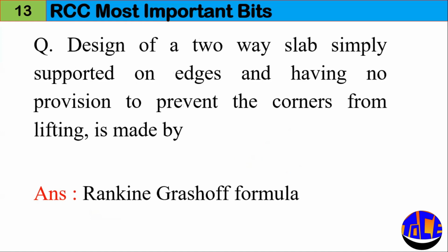Question number 13. Design of a two-way slab simply supported on edges and having no provision to prevent the corners from lifting is made by Rankine-Grashof formula. So using Rankine-Grashof formula, this Rankine-Grashof provided coefficients for two-way slabs.